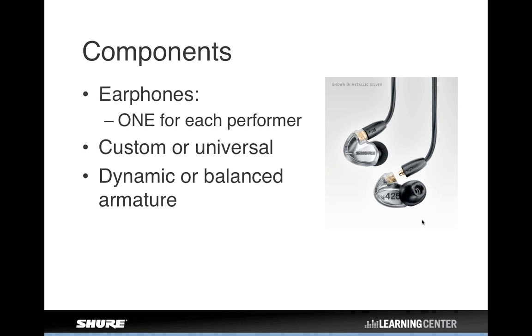Two different types of technologies are used inside of the earphones, either a dynamic driver or what's called a balanced armature driver, which is a technology that's kind of borrowed from the hearing aid industry. The difference is that dynamic drivers tend to be more inexpensive, so more the entry-level models might feature a dynamic driver, but the frequency response is somewhat limited. The balanced armatures typically are more sensitive with higher output, wider ranging frequency response, and can be made much smaller, but they're a little bit more expensive too. Again, just more options that are out there.